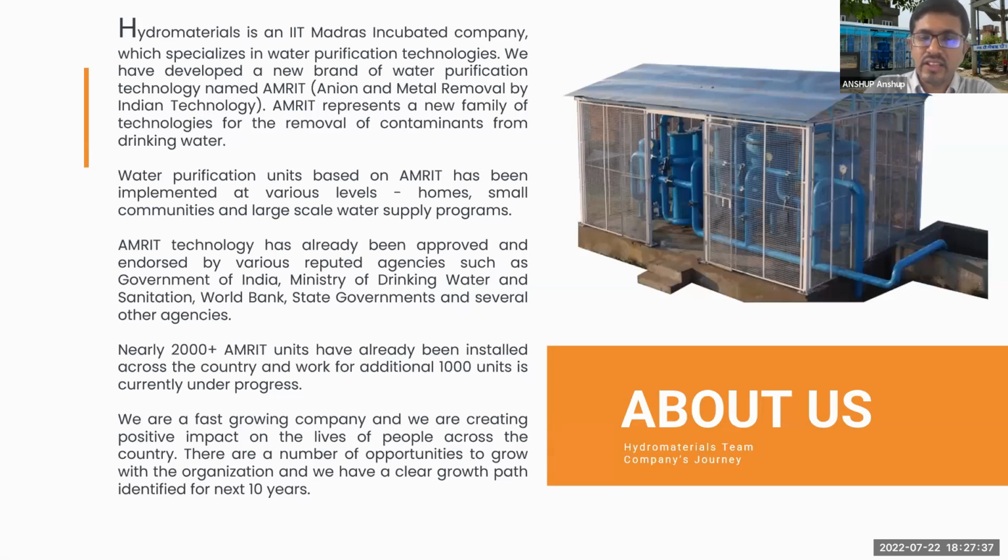In one such initiative, we were asked to provide clean water in the state of Punjab, which is in the northern part of the country. The way the scheme works is that you have a water supply scheme, which is centrally located in a village, where you have a pumping station and a reservoir at a staging height of about 20 meters. And from there, the water supply is done across the village.